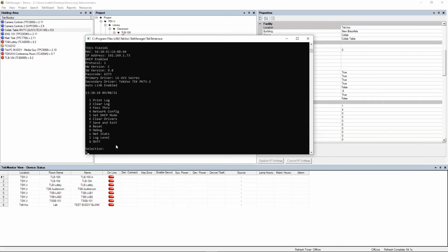And after that, we have debug mode. This again prompts us whether we're getting the serial data in hex or not. For this specific device, I believe it's not. We'll select channel 1. And as you can see here, we can see the serial information or data that is going out of the TEK monitor and what we're receiving from the device on the other end.